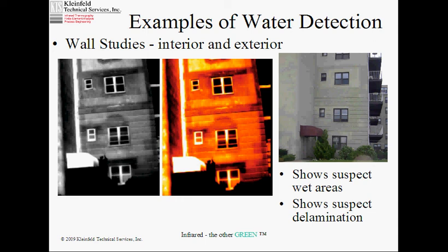This bright area, these bright areas represent delaminations. A piece of the wall that is not well attached to the part of the wall behind it physically is also not well attached thermally. So that if you have, and now here's your wall, I'm going to turn it so you can see the cross section. There's a piece of delaminated wall, you got the sun shining on that. The heat flow path for this section is into the skinny little piece and then around the delamination.